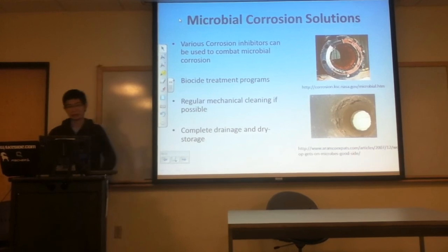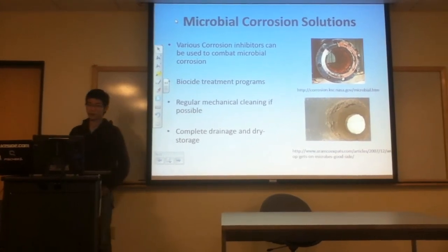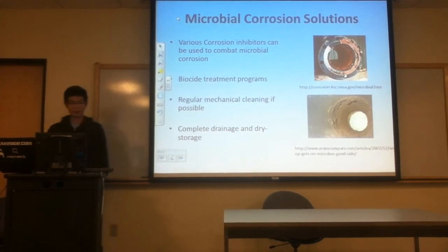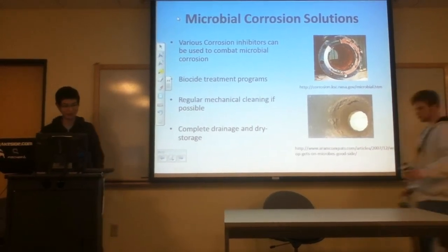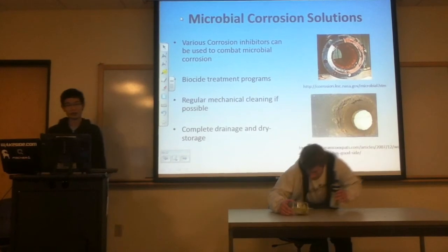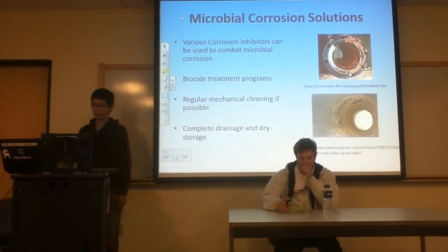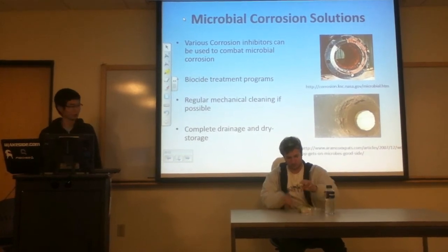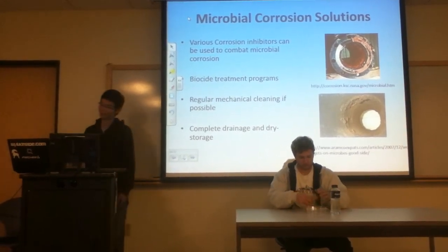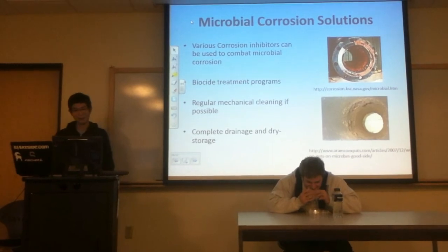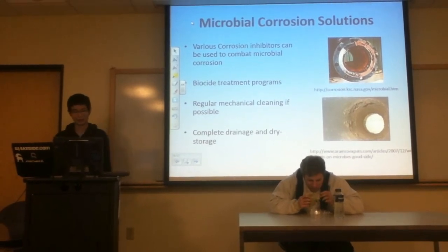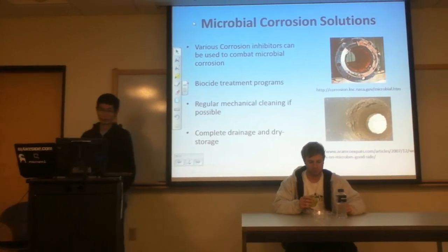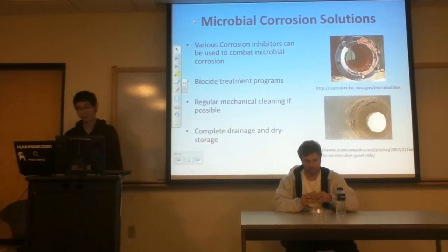And I found some solutions to the microbial corrosion and wet corrosion. There are many ways to protect the metal. The first way is corrosion inhibitors, and another way is biocide treatment programs, just like killing bugs.